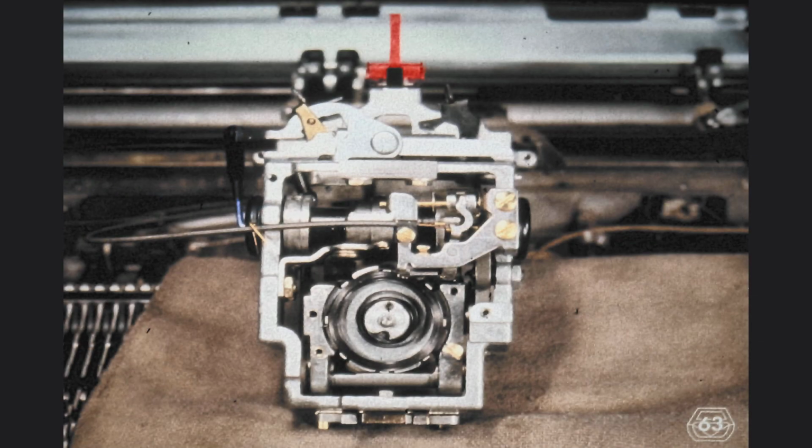This is a view of the underside of the carrier, with the rotate spring exposed and clearly visible. The rotate spring supplies the force needed to carry out all of the negative rotation of the element. Negative rotation of the element is clockwise rotation for an observer placed above the typewriter. From this discussion, we can see that the Selectric uses both positive rotation and negative rotation for the element, so